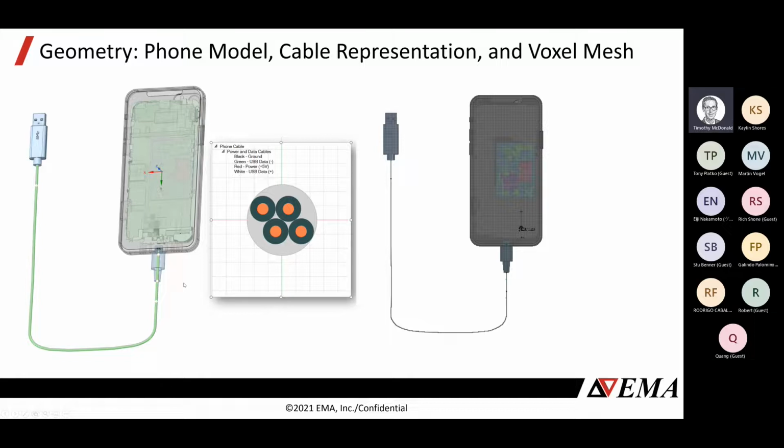The way EMA3D represents cables is unique. The path of the cable is tracked in 3D, but what is inside that cable is defined in 2D. So that reduced dimensionality, along with a modification of transmission line theory, lets us specify things like shields, foils, braids, conductors, branches, all of that in 2D world, and cast that onto the path of the cable in 3D. And we can co-solve those two solvers simultaneously, time step by time step. So for users, that's a huge time saver.